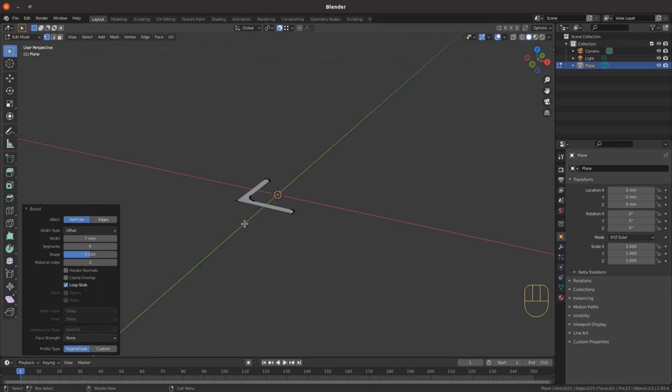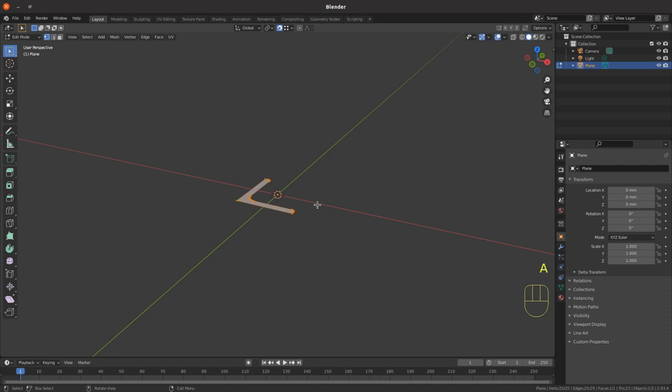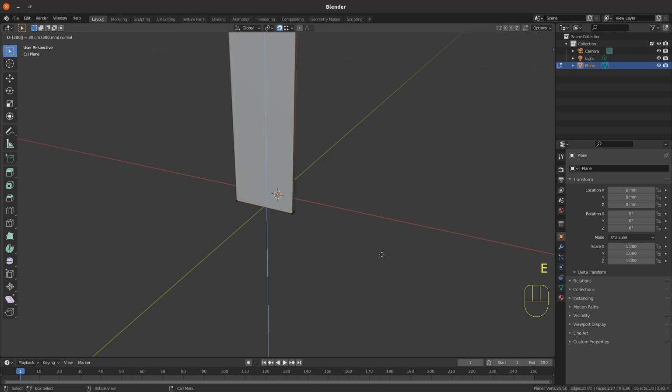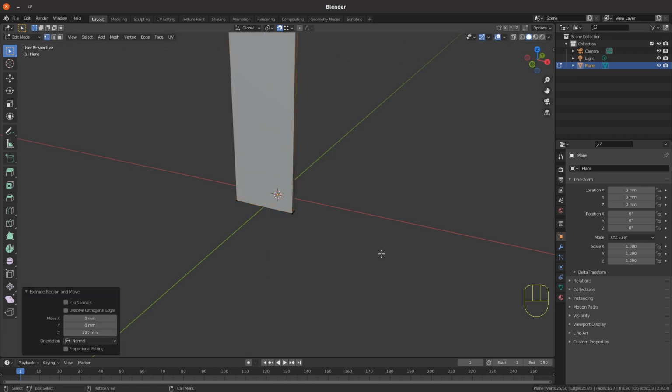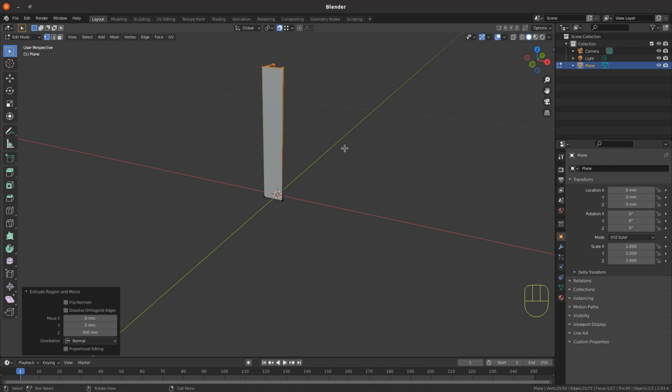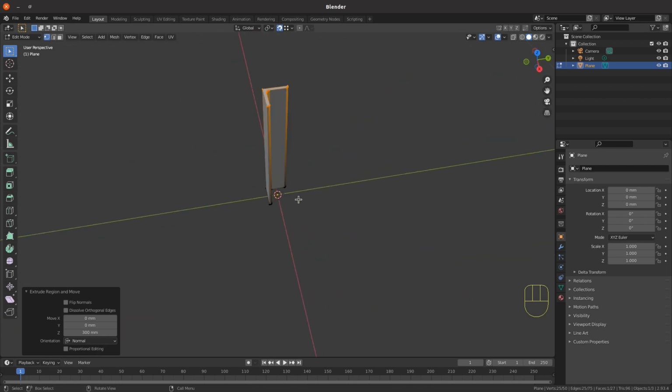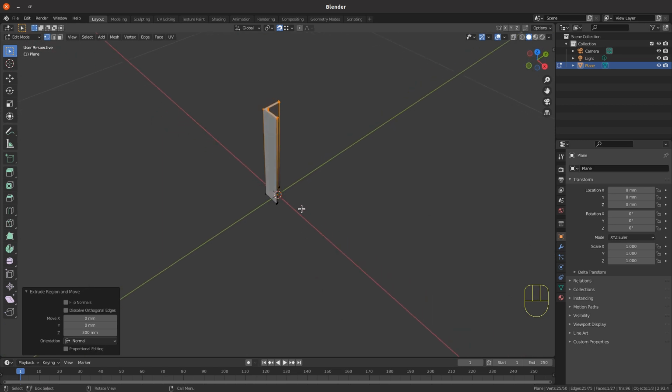This represents the bottom of the angle iron, and as we've done in the first video, we'll just extrude this because it's already got a face, it knows which way the face normals are, so we can extrude this 300mm. So select all by pressing the A key and all the vertices will be selected, and then press E to extrude and 300 as the length we're extruding, and enter. If you just zoom out a little bit more, you'll see we've now got the angle iron profile made.